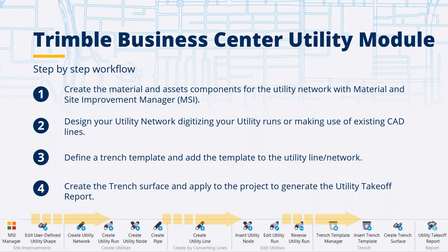And all of this can basically be finalized in the generation of a final report where the user at the end can see the extent, the trenches, the volumes of the materials which have to be removed or moved, the number of elements which are needed, for example manholes, types of pipes, diameter per type of pipes.